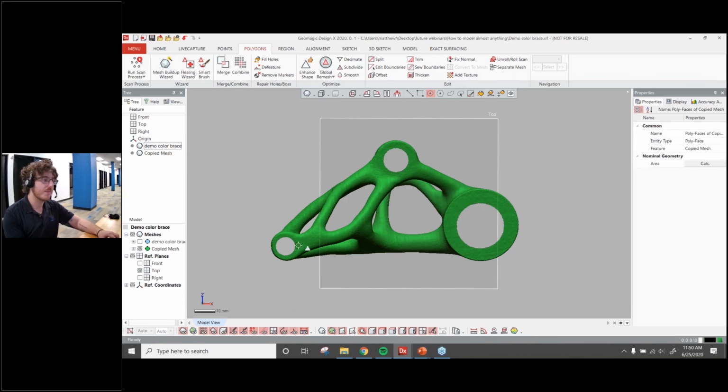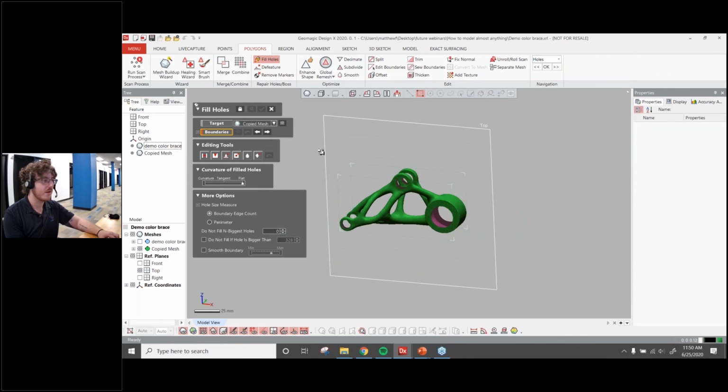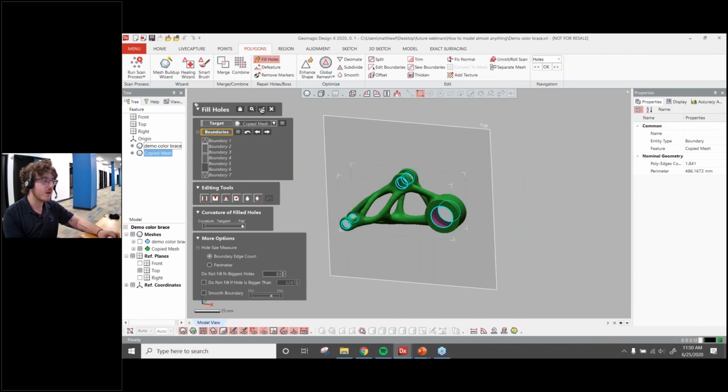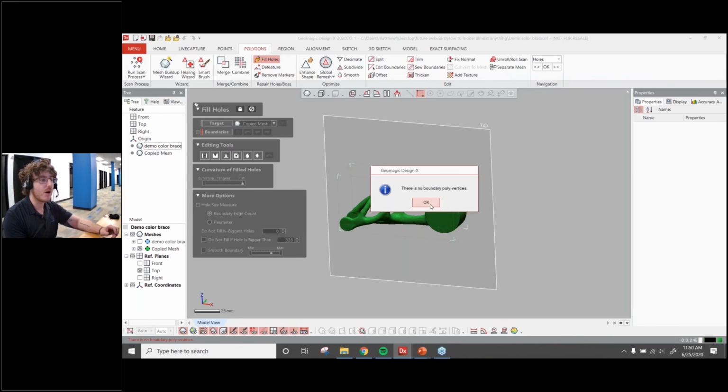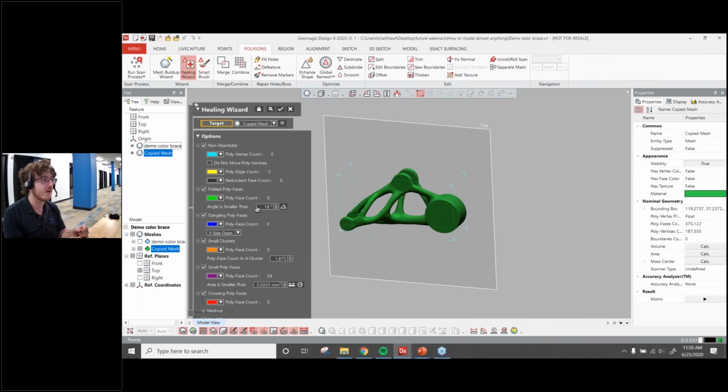And I'm just going to delete these. So direct editing onto the mesh, and then just using a hole fill to fill everything back up. Because I want this to be watertight when using the auto surface tool. I also want to make sure that it is properly healed up and we don't have something called non-manifold sections. Essentially, non-manifold sections are where surfaces or meshes, parts of it blend together, something that we don't really want when we're trying to get an exact one-to-one mesh.